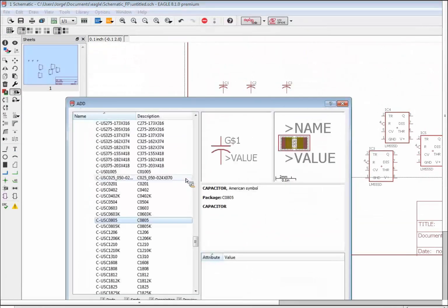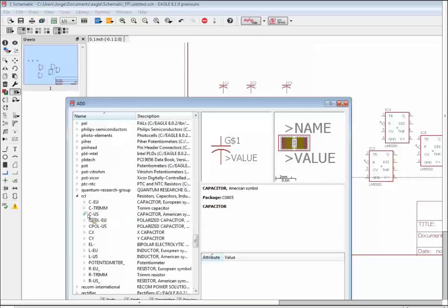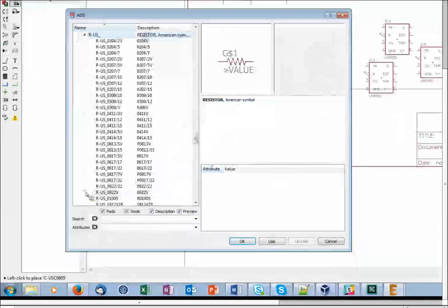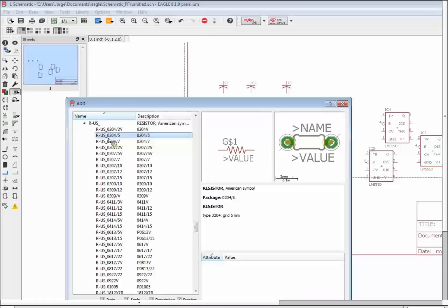Going to go ahead and bring in my resistors. For resistors, you'll see something similar. In the case of resistors, what you'll see is that you'll have, again, the width by the length, so 2 millimeters in width by 4 millimeters in length, and then the number after the forward slash is the separation between the pads.